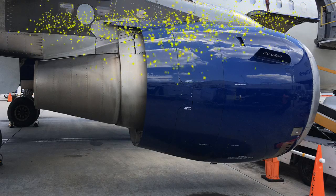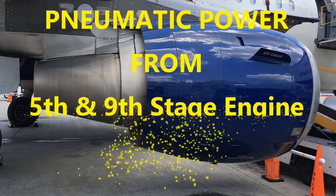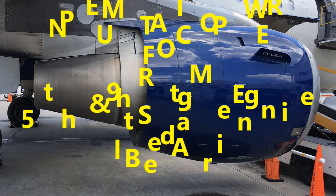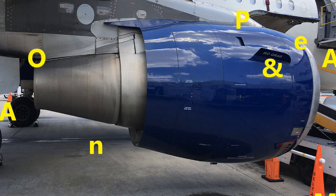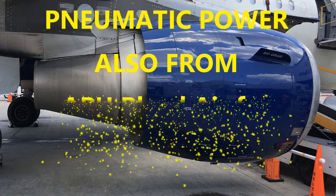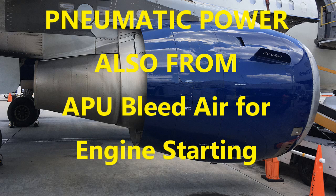So that leads me to mention the suppliers of the air. It's going to be coming from the engines, and it'll be 5th stage and 9th stage air, all from the high pressure compressor. The BMCs also control whether it's taking the 5th stage air or the 9th stage air into the user systems, depending on where the plane is. If it's at idle, or there's just not enough power, then it's going to draw from the 9th stage, where you have a higher pressure than at 5th stage.